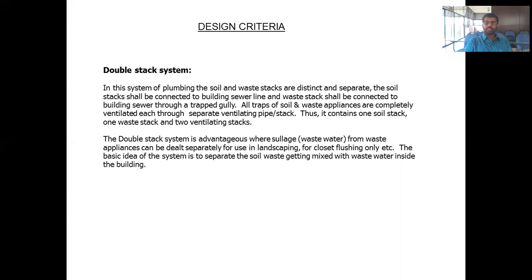The basic idea of the system is to separate the soil waste from getting mixed with the wastewater inside the building. So the two should not come in contact. That's why we use a double stack system. It is very advantageous and easy for further maintenance or servicing also.